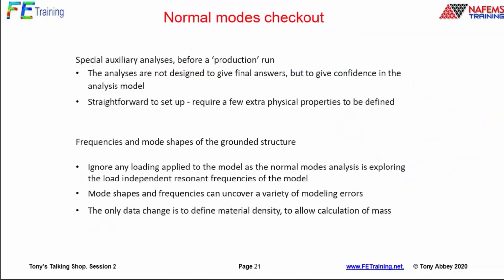So I've talked about the normal modes checkout. It's so useful. So as part of this checkout sanity check, as well as checking these maximum stress numbers, maximum deflection numbers, as I get older, I make more mistakes. I almost always commit my static analysis now and do a quick normal modes run on it just before I even bother to check it out. So I'm going to add this in. It's such a powerful tool.